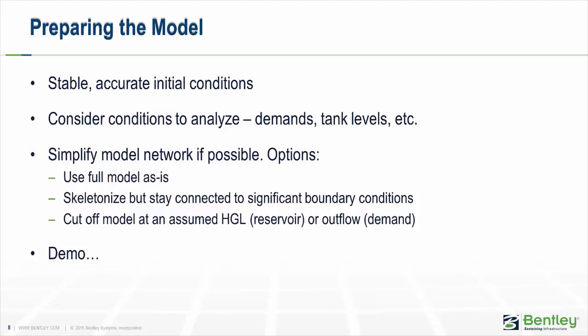Then consider, what kind of conditions will you be using as that starting steady state period? Will it be at a time when you're experiencing your peak hour demand, your average day? Should I start it with the tanks at a low level, a high level? So it's something to consider.